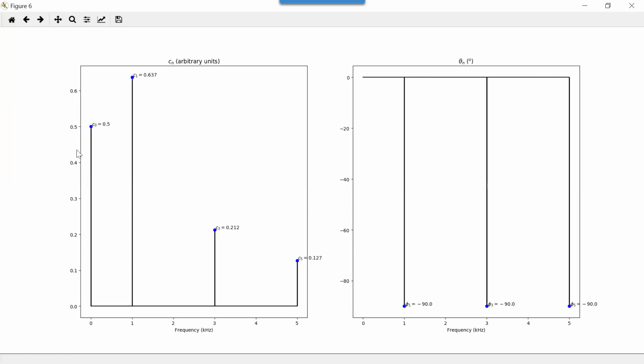Now, what would the low pass filter look like? Well, I have to have a low pass filter in here that's trying to attenuate all these harmonics. These are pretty close, right? And so the higher order the filter, the sharper the line.